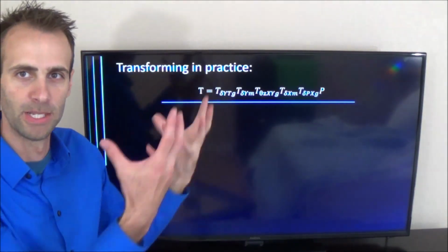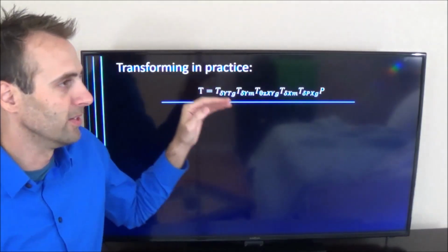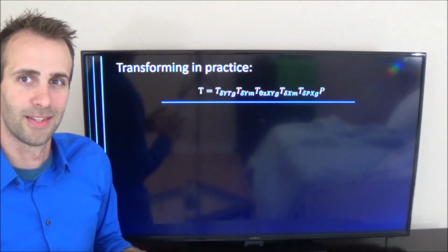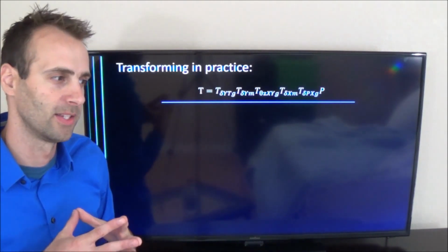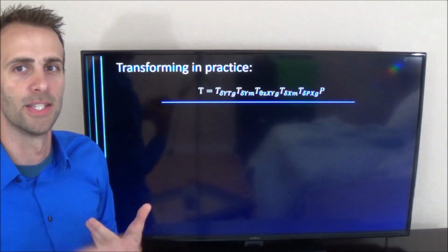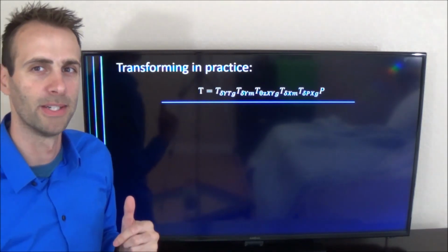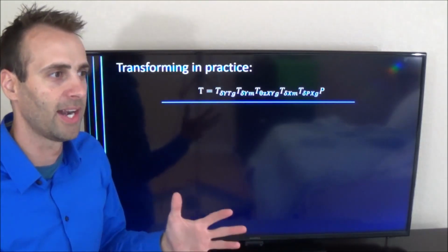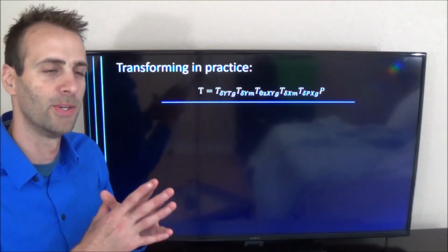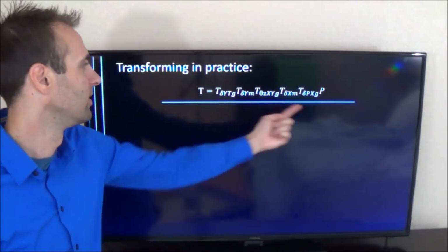How do I position my machine? There's no quick answer for how to solve inverse kinematics. This is sort of a game of logic. There are analytic solutions, there are numeric solutions, but just beware, there's no quick answer for how to get my machine to go here.